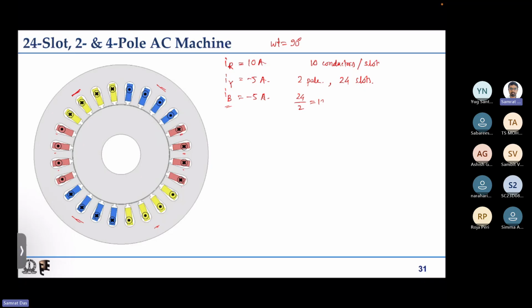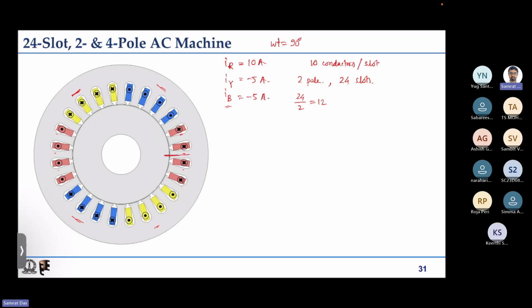Let us start from 0 degree. So this is our 0 degree. Let us construct one Amperian loop. So here it completes, and this is how one loop can be constructed. The direction can be anything, clockwise or anti-clockwise, but we have to fix that. Now it is possible for us to write Ampere's circuital law in this loop. So basically H dot dl equal to the enclosed current, right?